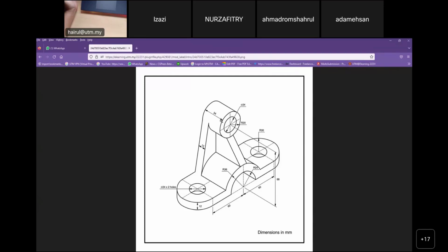at the top cylinder, it would not be stiff enough. And when we apply force, in holding a load, holding a structure or component, like holding a shaft passing through here, there will be reaction force. So this one as a base is not stiff enough if we don't have the rib wall. So in Solidworks, we call it a rib at the middle here.